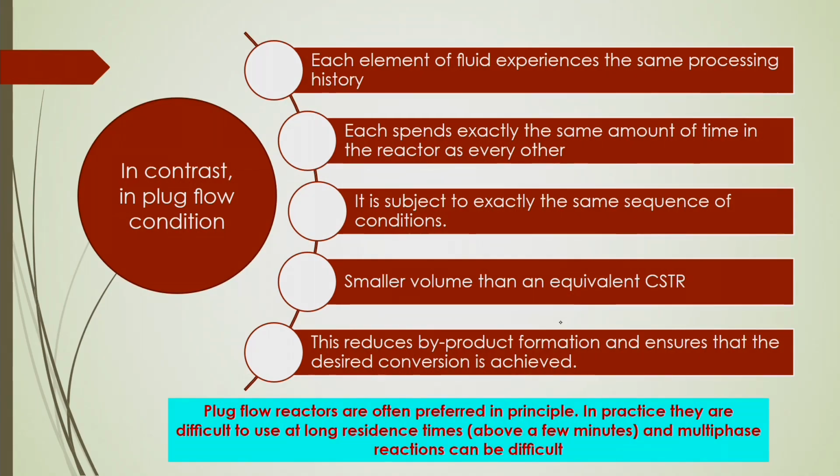In practice, they are difficult to use at long residence times, above a few minutes, and multi-phase reactions can be difficult. So, all reactors have some advantages and disadvantages. Though it has a reduction in back mixing and can give you a better yield, sometimes handling these micro scale reactors is very difficult, and multi-phase processing is also difficult in this type of reactor.